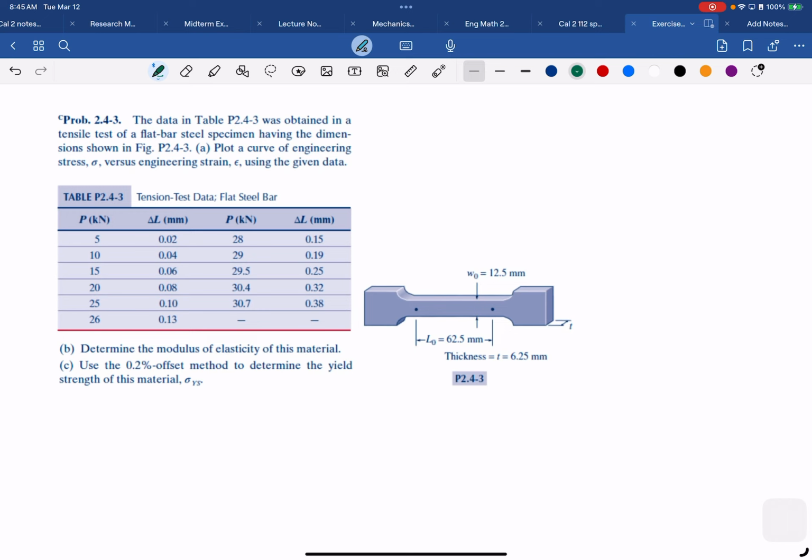Okay, and after some scaling, I make the step exactly 0.001, and you can see that at 0.001 it is precisely at the 200, and this means that you can directly get the modulus of elasticity, which is 200. So this is MPa, megapascal, so multiplied with this, it should be 200 gigapascal, which is, I think, quite okay.